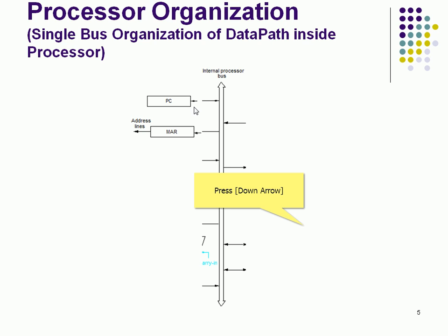So it has a direct link with the memory, going via the address line. With the help of this address line, it goes to the memory. There it searches that location, and once it is available, it is loaded onto the data bus or instruction bus, which reaches the internal processor bus, right? Here the IR will welcome it, as we just discussed previously. The MAR is the address register, and we have one more called MDR, the memory data register.